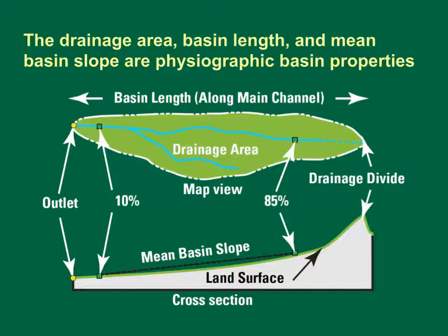Thus, it is the area of the basin footprint on a map, not the area of the land surface within the basin. At highway sites and in developed stream basins, the drainage area may be dependent on the storm sewer drainage system as well as the topographic divides.